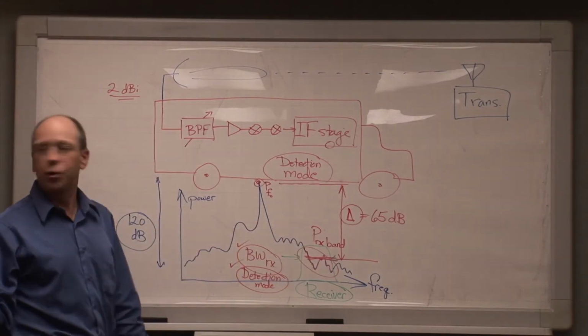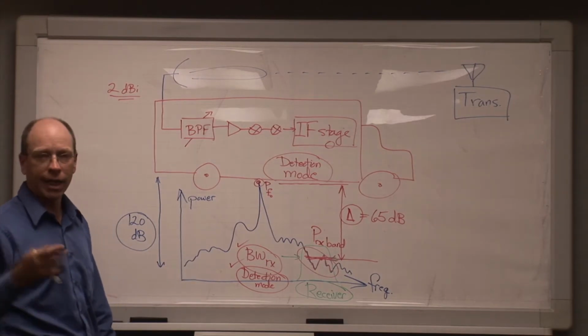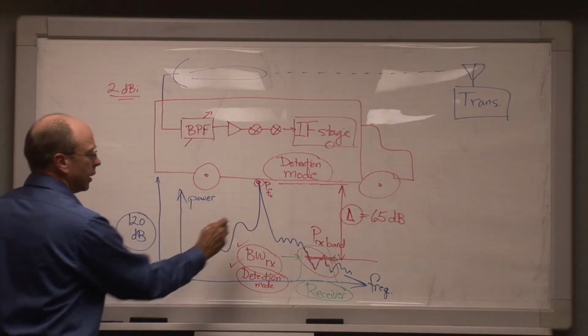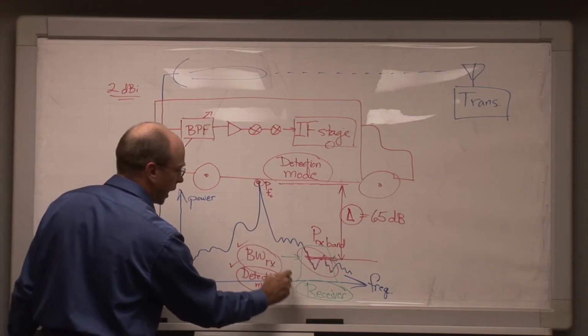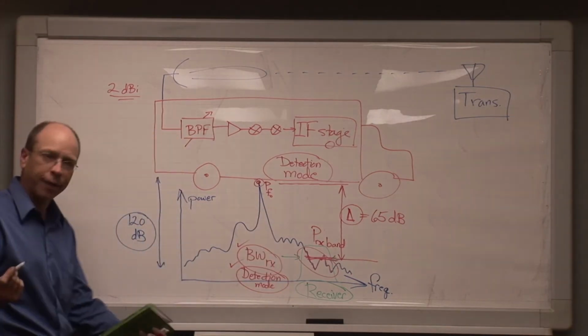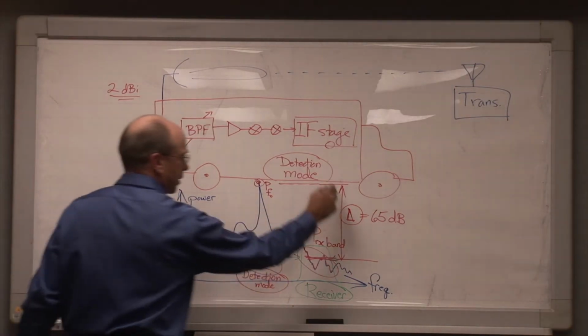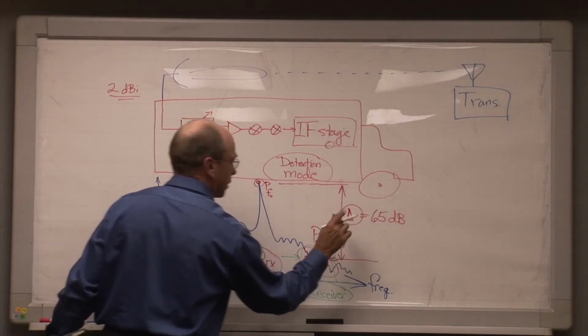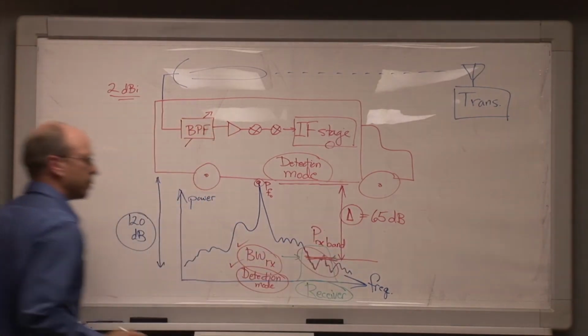It could be that we're getting not co-channel, but adjacent channel bleed over. In that case, all we do is measure the communication channel and then just follow it down into the adjacent channel part of the spectrum. But the point is still the same. We're going to see how far down this delta is in this part of its emission spectrum.